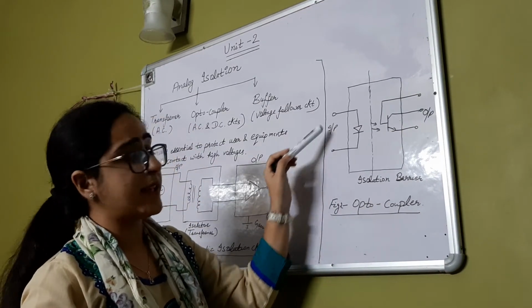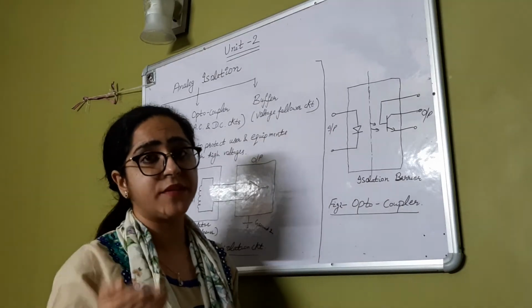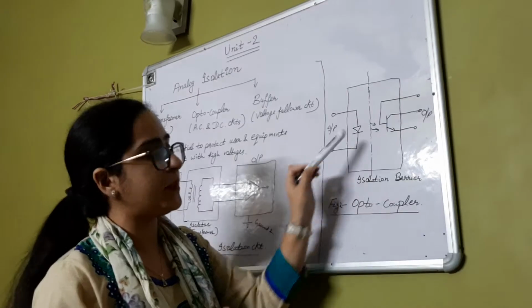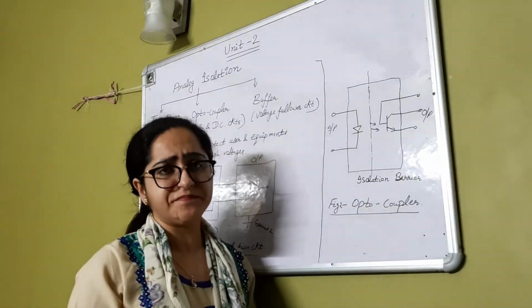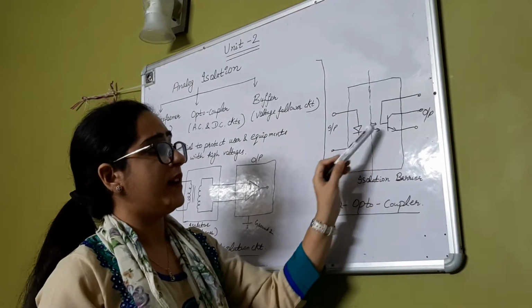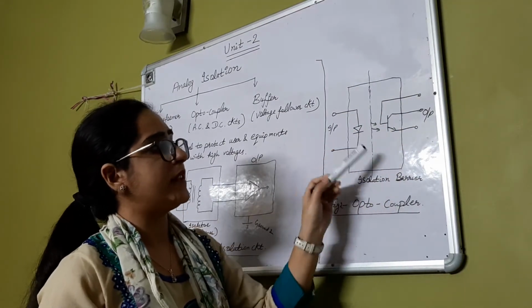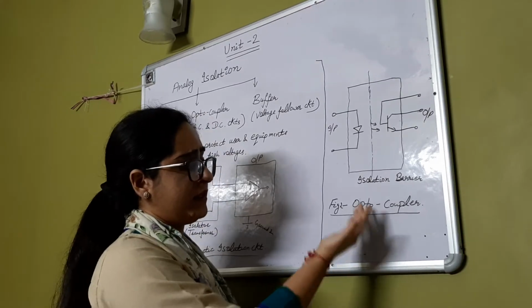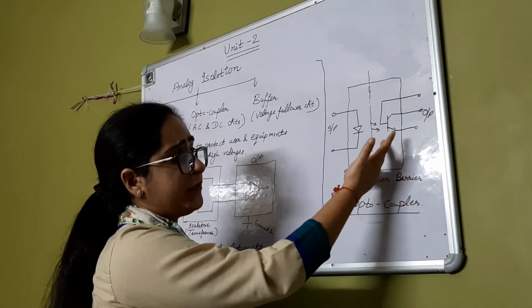Because in analog input, the value will be changing at certain times. So at that time there will be slow transmission or a slow detecting rate, due to which there will be certain problems. So this is just a small disadvantage of using this optocoupler or the phototransistor there.